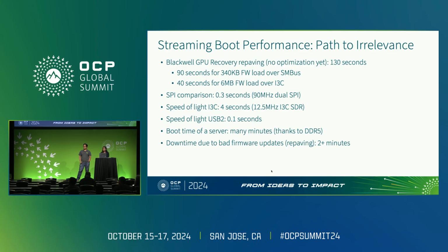So just one quick question. We went from local storage going slowly to now streaming it from somewhere. So now is there latency to get the image? That adds to the whole equation about how long the system takes. And if you have a fallback, for example, recovery, now you have to go and fetch the fallback firmware too. Does that latency matter? Do you prefetch them both and then toss one away?